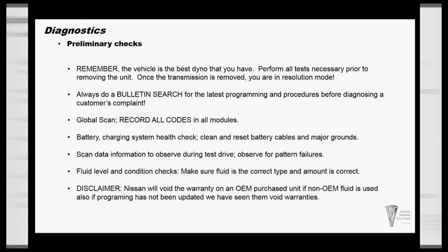Remember, the vehicle is the best dyno you have, so perform all the necessary tests and gather all the data that you need before you remove this transmission. We'll always want to do a bulletin search, make sure the latest programming has been done, and make sure you focus on the customer's complaint to resolve that complaint.